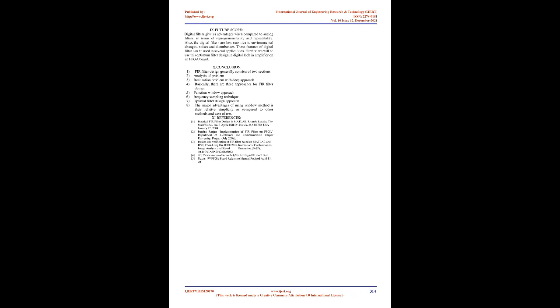8. FPGA implementation. For trying out the FIR filter built in the Filter Designer tool of Matlab, we created a coefficient file from Matlab and imported it into the FIR IP core in Xilinx Vivado. After importing the coefficients file, we integrated the IP into our Verilog code. We also used the Integrated Logic Analyzer IP of Xilinx to observe the simulation results of our code. The code is written in Verilog HDL.